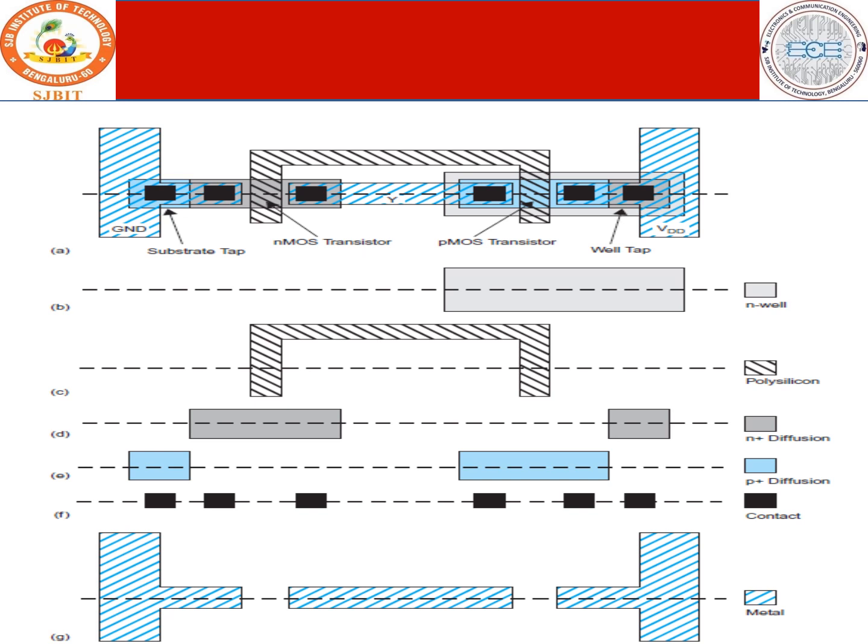Next we have the polysilicon mask. So only in this area you can see polysilicon being deposited, or N-well can be avoided. Masking can be done here and only here N-well can be created. It depends on how this particular technology is being used. Next type of masking is the N-diffusion mask. So since you are constructing it on a P substrate, as we have seen from the earlier diagram, this whole thing requires N-diffusion. Next is P diffusion.